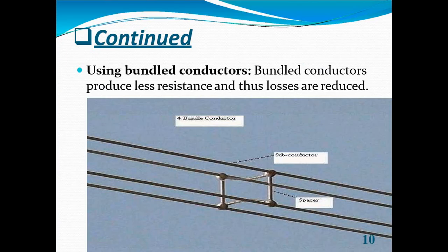And by increasing the conductor spacing, meaning increasing the spacing between the conductors, the voltage at which corona occurs is raised, hence the corona effect can be eliminated. However, spacing cannot be increased too much, otherwise the cost of the supporting structure may increase to a considerable extent. Supporting structures like bigger cross arms and supports may be required, so the cost may increase.